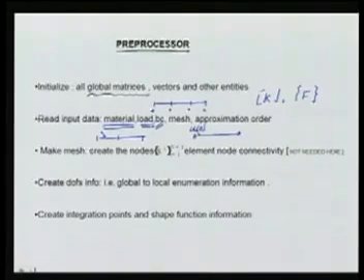For example, if it is Dirichlet, then I have to give what is u at 0 as input data. If it is Neumann, then I have to give what is the tensile force at this end. If it is Robin, then I have to give the spring constant of the attached spring and the initial compression of the spring. So this has to be done at both the ends, and all that information has to be read in from an input file into our program.